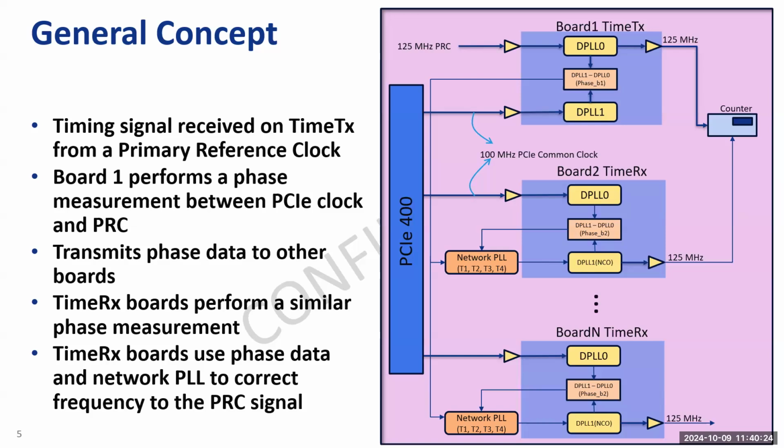You're right. But I think what we have to focus on is we have to assume that there's a PCI SIG requirement we've got to follow to be compliant to PCIe clocking. And so those have to be a must, right? Because of that, we have to make sure we test both scenarios of non-spread and spread. But over time, we may learn, hey, we don't need spread anymore because this eliminated the original issue, and we have different ways to now mitigate what we were seeing before. Yes, I agree with that statement.